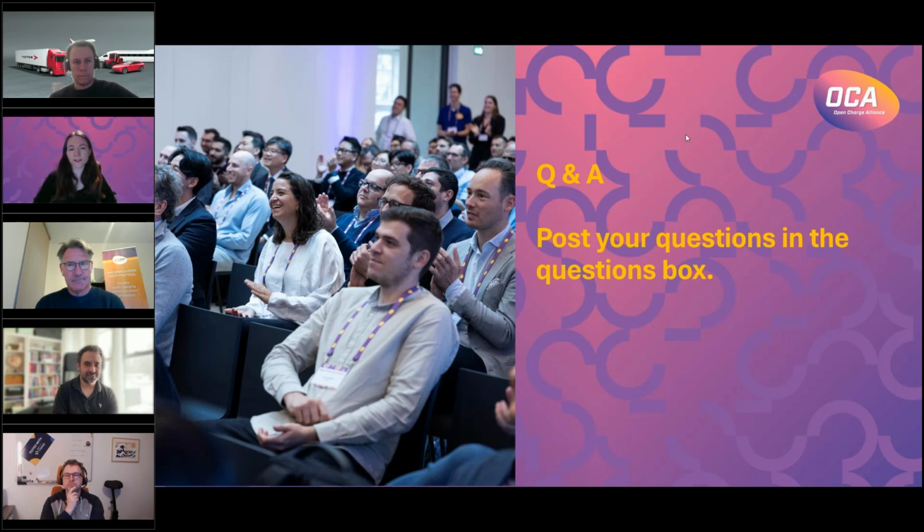Is anyone hosting a publicly available 2.1 compliant charge point or simulator so that you could do interoperability testing via the internet? My assumption here is that the easy solution is to look at Everest. The Everest open source project now supports 2.1. It is still in the development branch, but I just learned today that it is going to be merged into the master branch. So the new release from next month will already have 2.1 in the master branch. So you can easily take Everest, run it in a Docker container, and use that for testing against your CPMS.